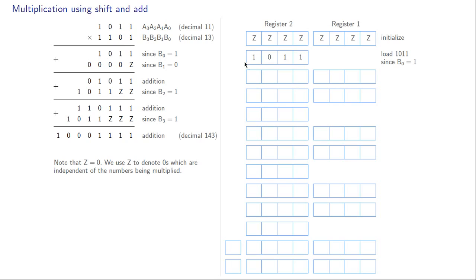And now we're going to add these two 4-bit binary numbers to get this result here. And this binary number is simply going to be copied to this part. Alright, so we have got 1011. In this case, of course, these are all zeros, so we have the same number over here. That is the result of the addition. Next, we shift this result right by one position. So this number 1011 has appeared here now, 1011, and 10 has got padded from the left.